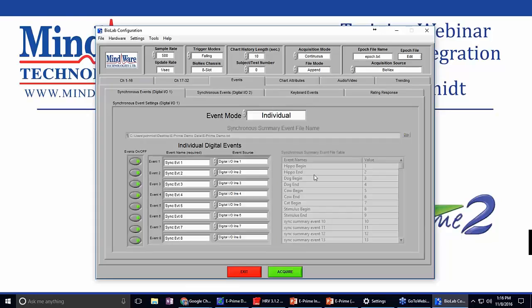If we select this, basically what this is doing is giving you 8 events, basically 4 in 8 slots, and they can all be fired simultaneously instead of 255 events that cannot be simultaneous. It's based on the bits within a byte, so a value of 1 sends on line 1, 2 sends on line 2, and 4 sends on line 3. It's binary logic, which we can't extremely cover here, but that is how you would do so, and that's what it's used for.